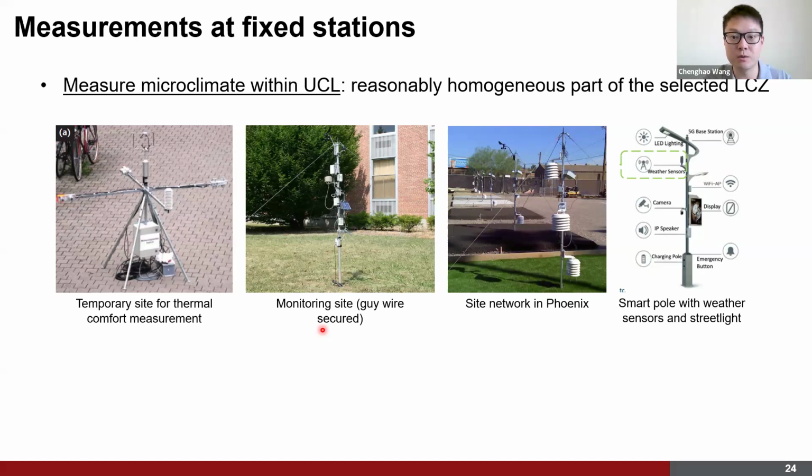If you're using a low-cost sensor, the sensitivity is around 1 ppm. Basically, every time you measure a signal, it is actually a high peak of methane emission. But if we're using LiDAR, we can detect changes of several tens of ppb in methane concentration. So it's much more sensitive than these low-cost sensors. So it totally depends on what you're trying to do with these sensors.